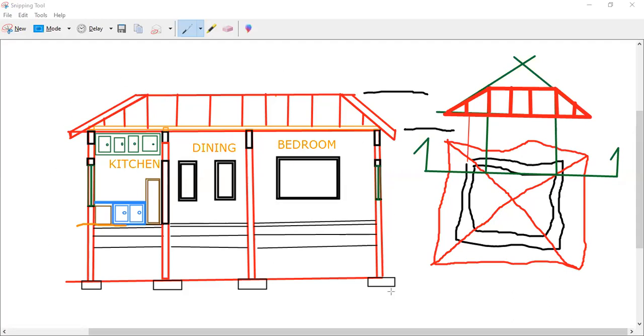Now, how would I go about drawing this in AutoCAD? The first thing would be to start a new drawing, set up your layers, your limits, your dimension settings if you're not using a template. And then you would start at the left-hand side. You would start here and engage orthogonal mode. Typically, they'll give you the details or specification that you need to use. In this case, we were told that the distance from the finished floor up to the ring beam right here is 2,800. So we know that.